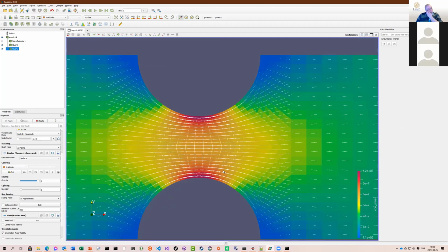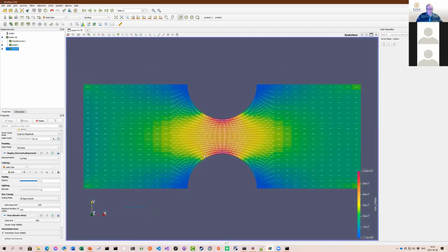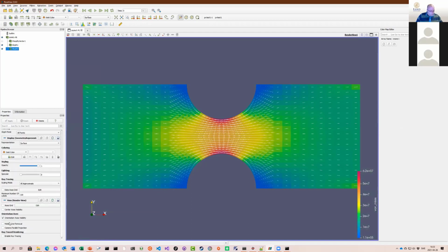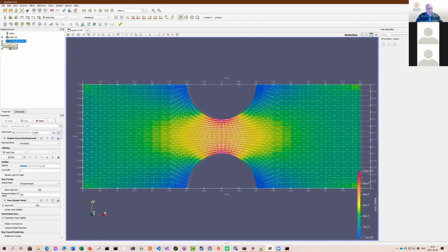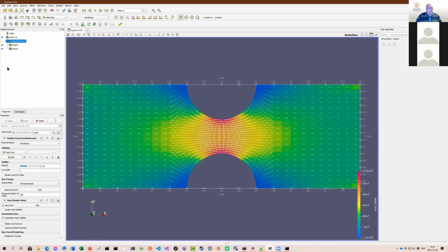So now we have the von Mises stresses here. We have to have an axis as well, like this. So now I think we have visualized everything we wanted to visualize here. So that's good. There's not so much more we can do. We can of course display the displacement field as well here. You could also apply the Mises stresses on the deformed mesh. That you can do yourself as an exercise.